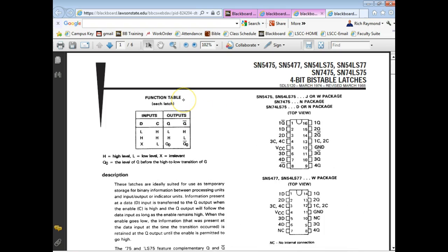Well, you say I'm going to stick to the U.S. standard, but a lot of this stuff is international. But you've got access to it, right? So you could look it up and get these international symbols. What's an AND? What's an OR? So anything you get from Siemens is going to be what? They're going to be IEC symbols. All the diagrams and everything you get from Siemens are going to be IEC because they're a German company, right? So Festo, if we started looking at the prints on the Festo line, they're using international symbols because they're a German company.